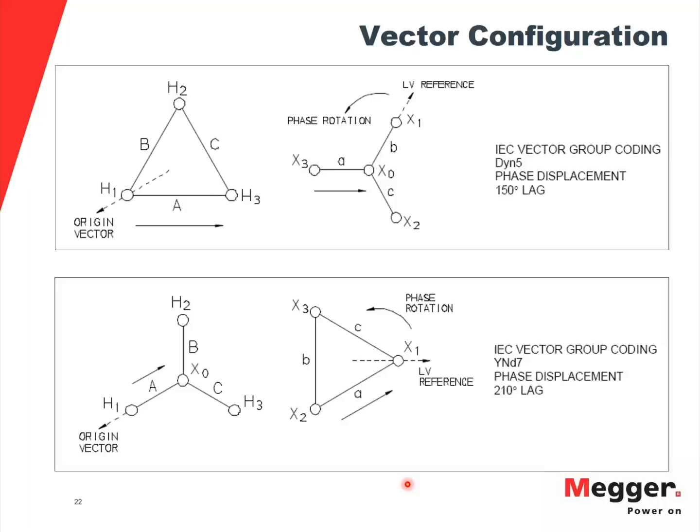you might get a good resistance reading from the DLRO, but when you go to take the leads off, you might run into a safety concern where it has not been able to dissipate the energy.